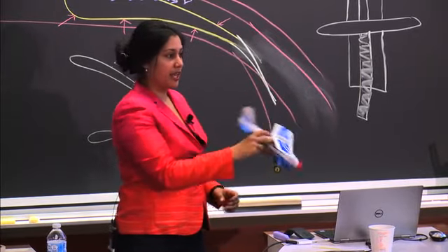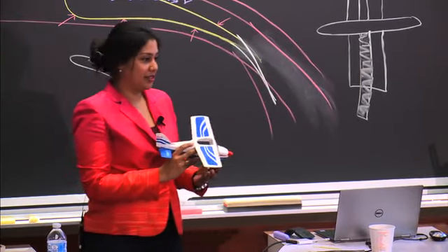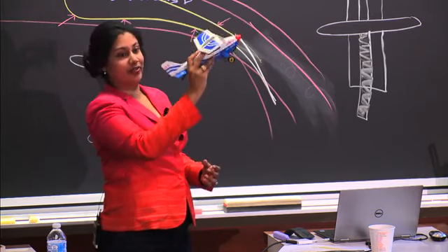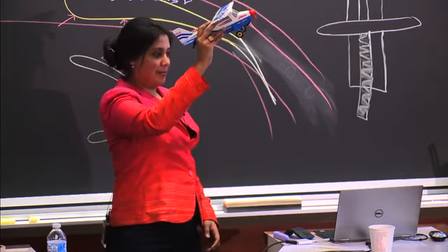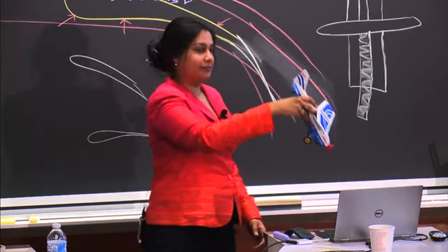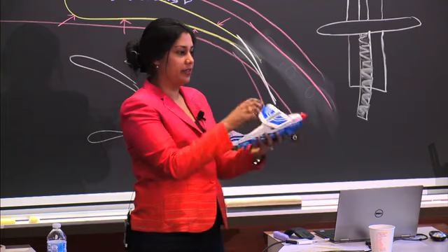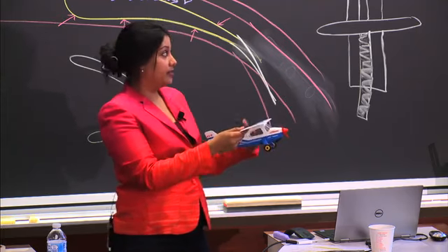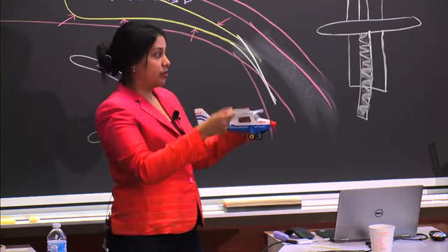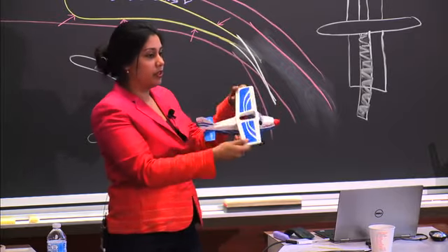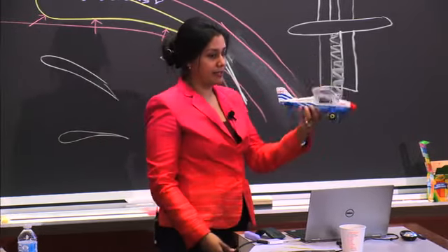So pitch nose down. You might hear that a lot in case you're getting close to stalling because your angle of attack is getting too high. They might say nose down or pitch nose down. You also have ailerons, which are out on the side of your wings, and those ailerons control the roll. That's rolling along the longitudinal axis.